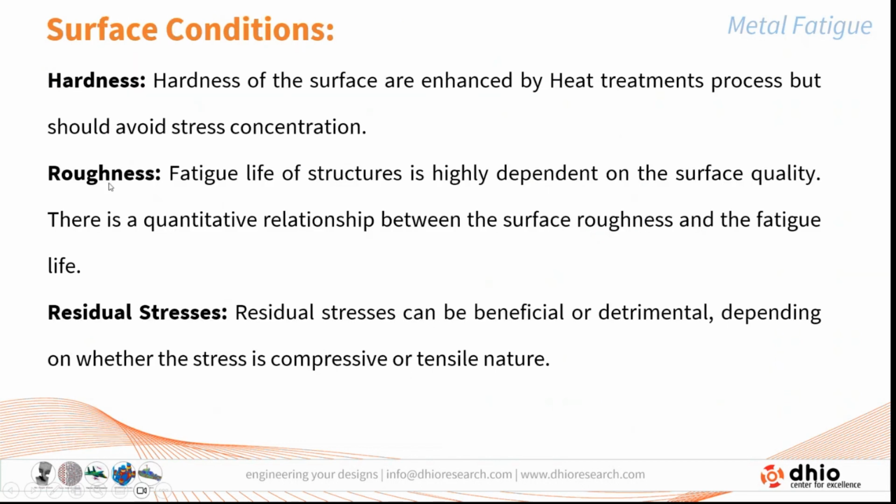Then based on the surface condition, how is the fatigue life going to be affected? The first is the surface hardness. Hardness of the surface is enhanced by the heat treatment process, but one should avoid stress concentration due to the heat treatment. Then the roughness, how rough or how smooth the surface is.